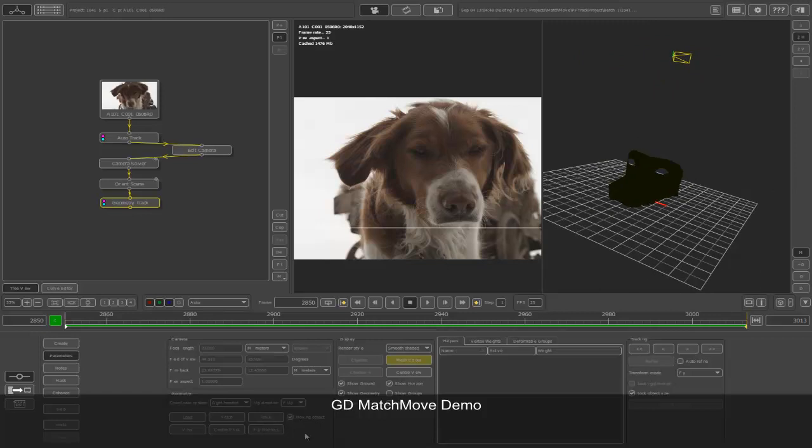The other main option I want you to remember is this moving object. Please make sure this is turned on, because we do not want the camera to move, so that it's a static object. We want the object to move, because the object is what is actually moving in our footage. So once we have set this and the right-handed option, we can check whether our focal length is right over here. Remember that if the focal length is wrong in the beginning when you created the geometry node, then it's totally a waste of doing any kind of track, because this value cannot be changed again once it is plugged in. So you'll have to delete the node and recreate a geometry track. So pretty much all the track you do is utterly of no use. So please make sure you do not do that.